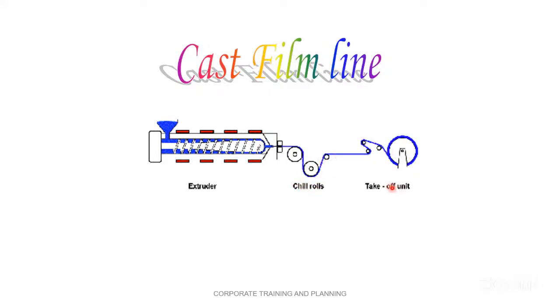See, take up unit. See here, it is not a surface winding. Now see, this is a center winding here. There is no other roll here, therefore this is center winding. Generally, for cast film, we are using center winding. Now you should know the difference between center winding and surface winding. Surface winding means, I told you, a very big roll is there. On that big roll, there are a number of bobbins around, like planets.